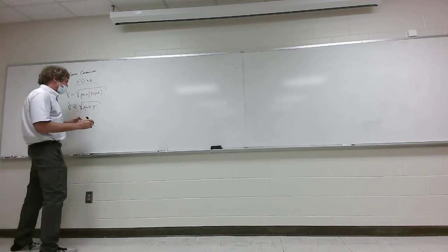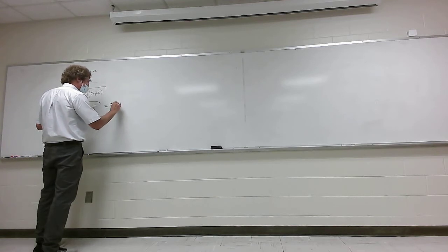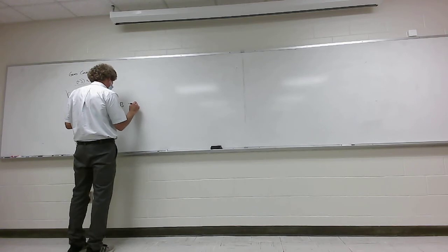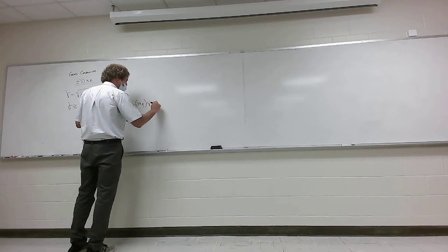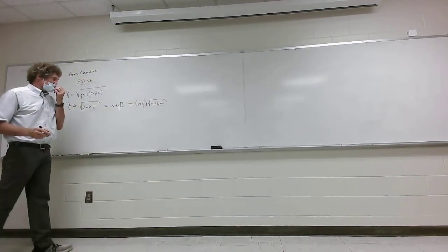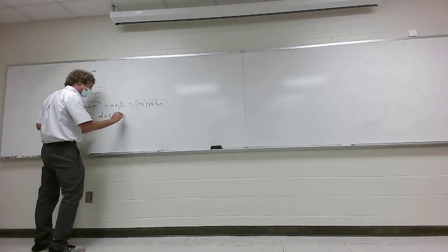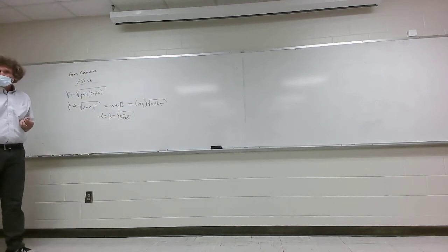And that means here that this is really alpha plus j beta, or simply, in this case, it's going to be (1 plus j) times the square root of pi f mu sigma. I've done this before, and it really means that alpha equals beta equals the square root of pi f mu sigma. That's all it is for a good conductor. We've done this before, I'm just rewriting it to bring you back so you've got a starting point.